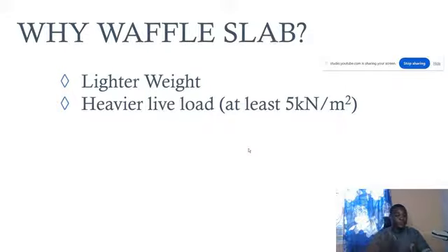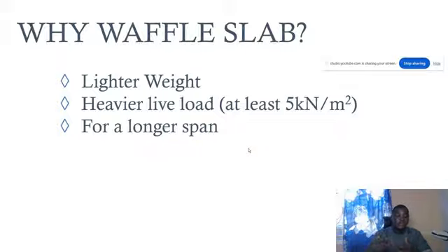That is when you can provide waffle slab and it will be economical. So it's very suitable for heavy live load. And because of that, we can say it can take a longer span. That is, the distance between supports can be as long as possible for a waffle slab as compared to other types of slab like ribbed or flat or solids.